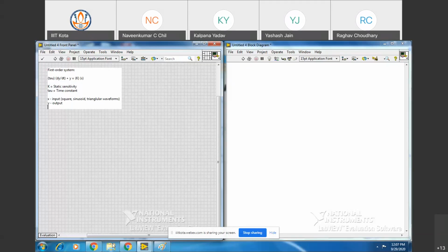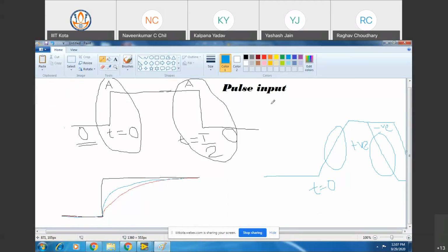It is almost complete. Okay. And if you remember the standard equation, V into 1 minus exponential raised to the power minus t by how much? For an RC circuit, it was R into C. You remember this equation? The voltage across the capacitor is this. Yes or no? You remember this equation from your 10 plus 2, I am saying. So V was the input voltage, a certain voltage you have applied from 0 to V. RC was one circuit.